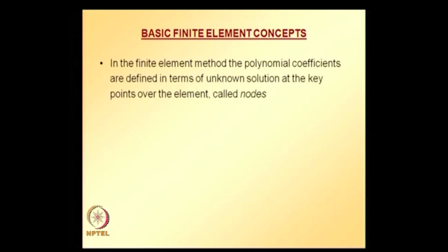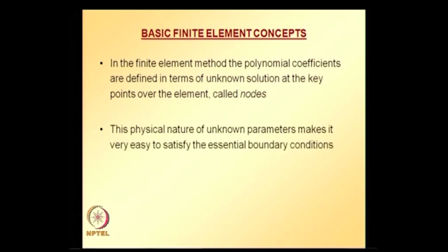In finite element method, the polynomial coefficients are defined in terms of unknown solutions at key points over an element called nodes. We will see more details of it in a while. So, the difference between classical approximate techniques and finite element method is that the polynomial coefficients are expressed in terms of nodal values in finite element method.